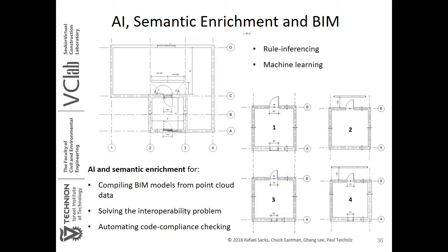That's the semantic enrichment. And we believe that this can be automated to a great extent, which will then mean that models produced from more or less any system may in the future be able to be imported into any other system, where the importing system will add in any implicit information that was absent from the IFC or other file it received.